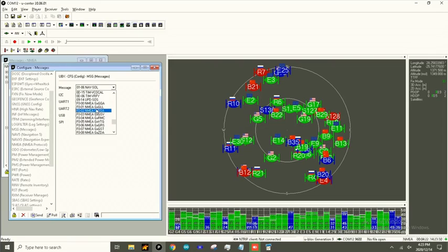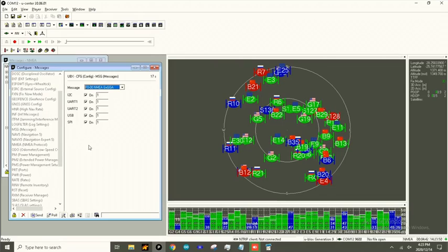These are typically, I believe, associated with each of the constellations. If I just click on GGA, you will see that these messages are enabled for all the output ports of the GNSS receiver module. So that's I2C, your 2 UART ports, USB, which is the one we're using, and then SPI.